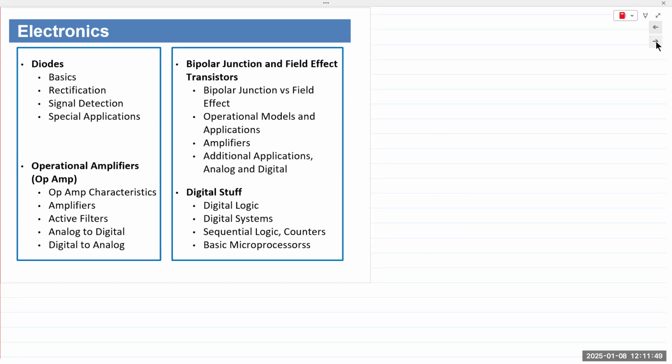Those are linear elements, and they are known as linear because the voltage and current have a linear relationship. If you increase or decrease the voltage, the current for that device increases or decreases proportionally, and vice versa, right? So the reason they're called linear is because voltage versus current has a linear relationship.